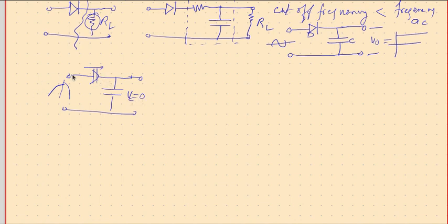This point voltage is 0, and this point voltage is increasing, therefore the diode is in forward bias condition and hence current will flow through the capacitor, charging the capacitor. The voltage across the capacitor keeps rising, and if the resistance is sufficient to produce enough current to charge the capacitor with the speed with which the input is changing or even faster than that, then definitely we can see the output having a similar rise as the input.